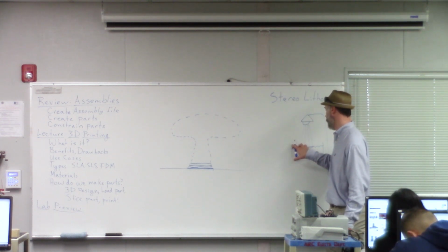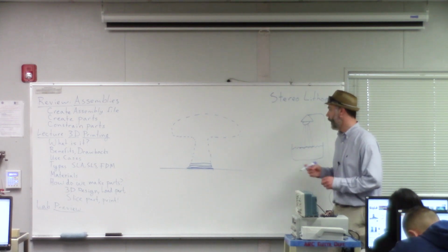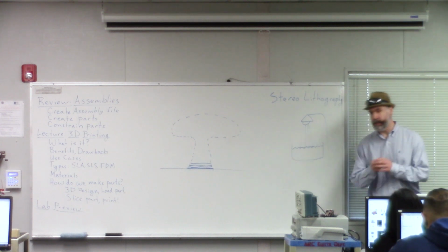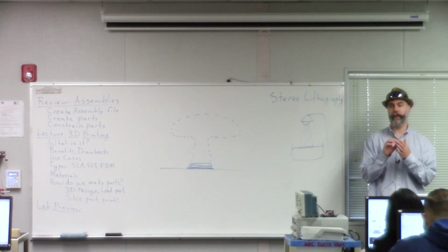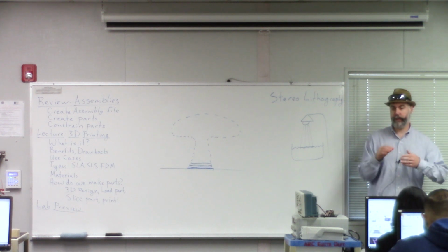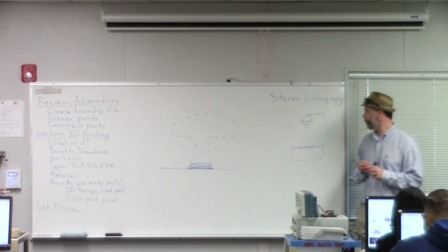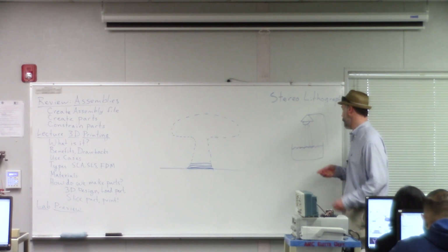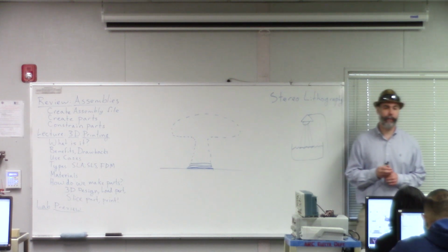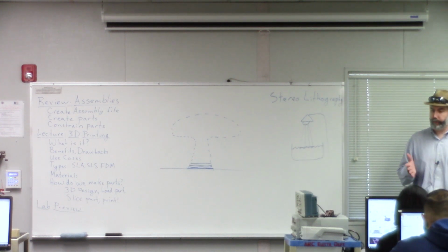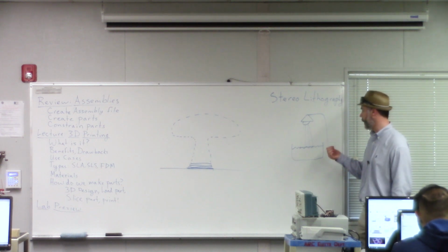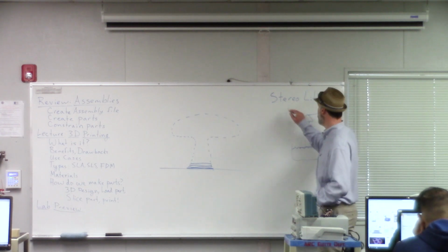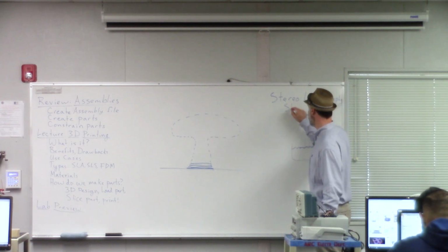That was one of the first 3D printing techniques that became available. And that is great for very, very fine details. You can make very, very thin layers, and they come out very smooth. Some of the drawbacks for that are that you have to have this vat of chemicals that's usually pretty toxic, and smells kind of bad, and I think that is a relatively slow process. But that was the first process, stereolithography, or SLA for short.